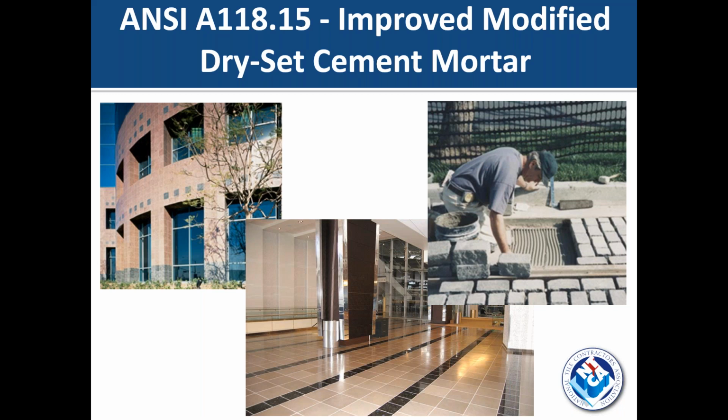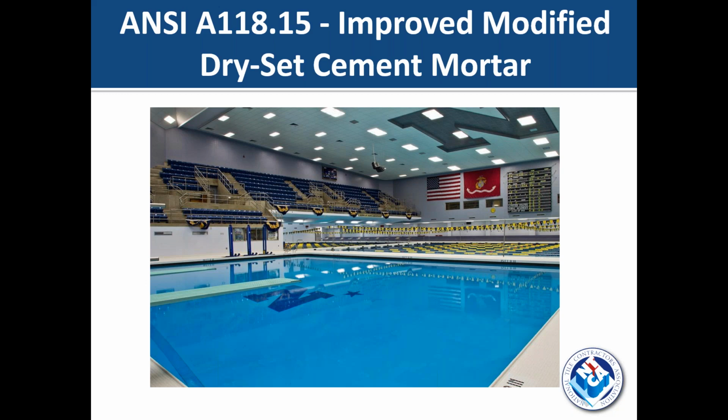There was a need to distinguish higher performing mortars from within the category of modified mortars. And so the industry came up with the new standard, A118.15, for improved modified dry set mortars. This provides another level of classification, and targets for this type of mortar include large format tiles, glass tile, submerged application, exterior veneers, and so forth. So this is the highest standard for a modified or polymer modified dry set mortar.